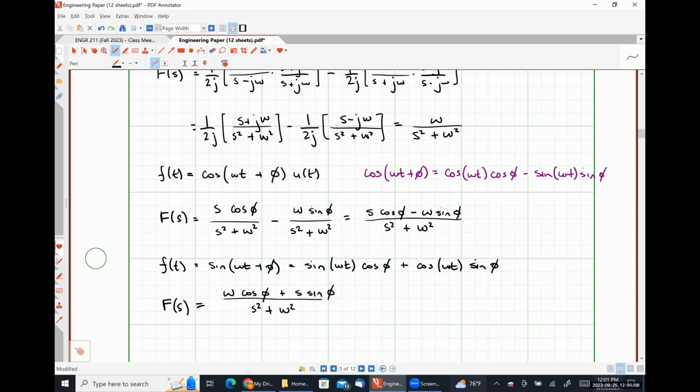So for a DC circuit, it's V squared over R or I squared times R. For a sinusoidally excited circuit, it is 1/2 the magnitude of V squared divided by R, or 1/2 the magnitude of I squared times R, unless you happen to have RMS phasors, at which point it's just the magnitude of the RMS voltage squared divided by R, or the magnitude of the RMS current squared times R. So when you have RMS values, you use the DC relationship. If you don't have RMS values, you need to add a factor of 1/2.